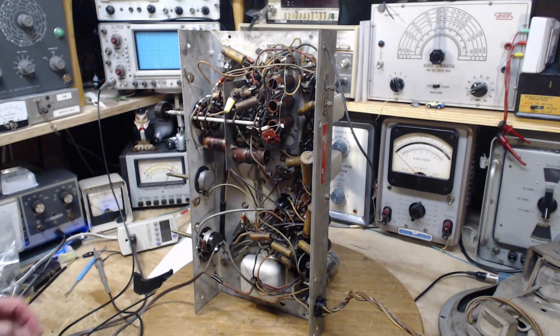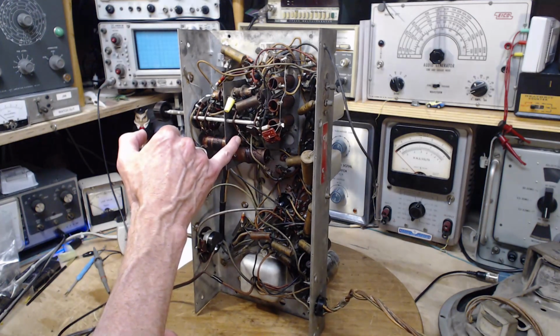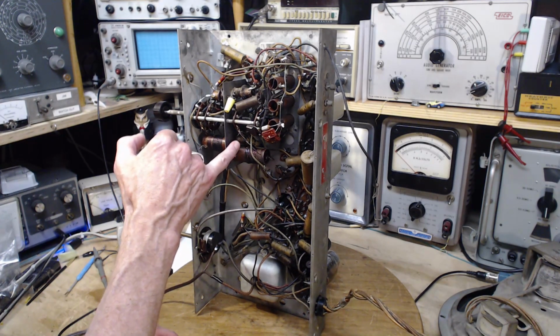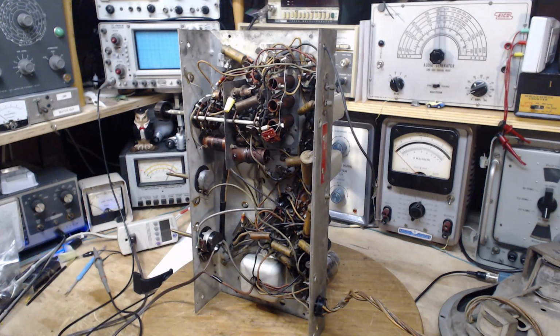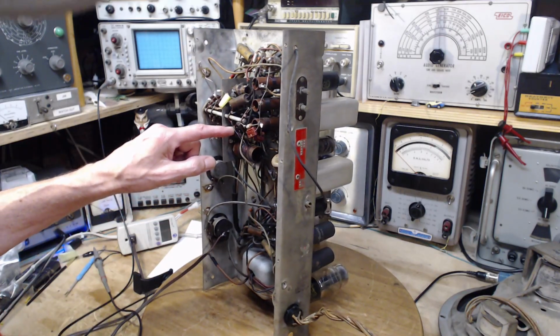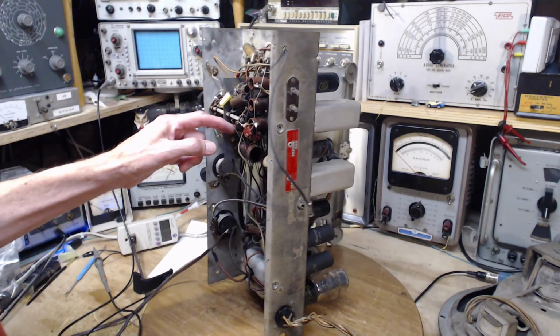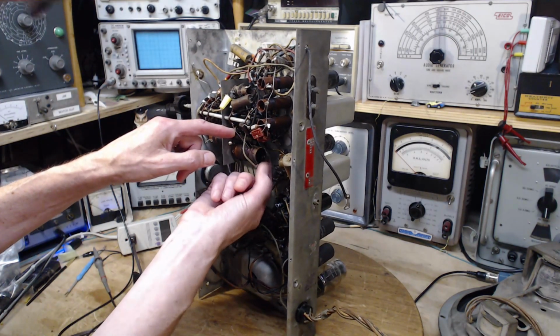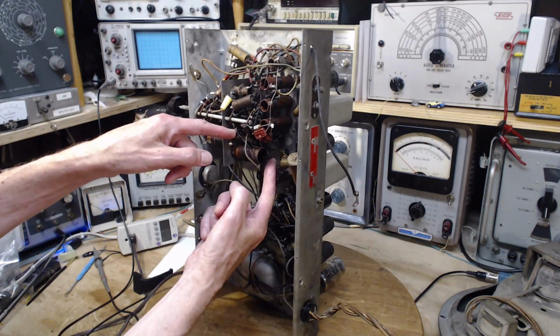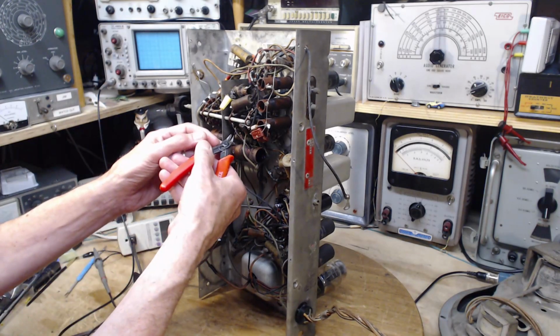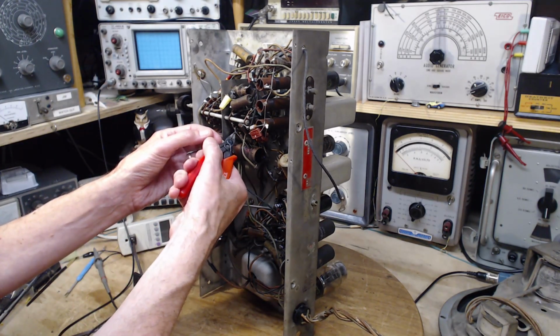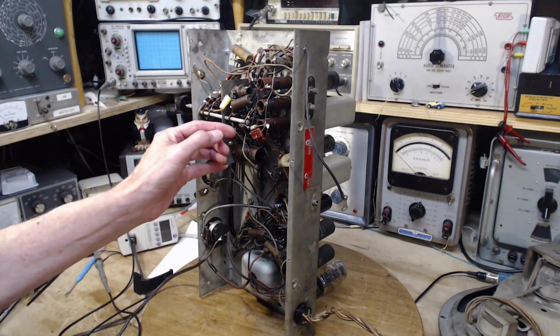Okay, now you've watched the flaming video, so we now know it's this capacitor. Is it just the capacitor alone, or has it gotten itself involved with this coil? We don't know, but my guess is just the capacitor. Yeah, let's see if we can get out of there. So one lead obviously comes here. The other lead looks like it's coming to this terminal here. Okay, so I'm going to cut this one. I'll leave a bit of wire behind to mark this terminal, but I'm going to go further.